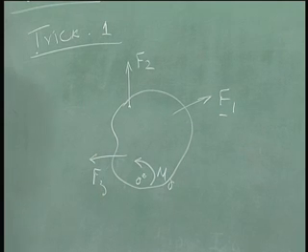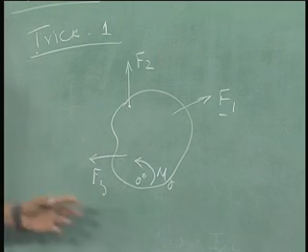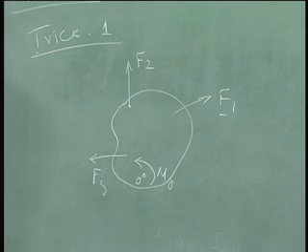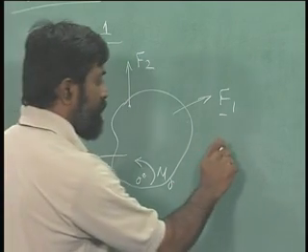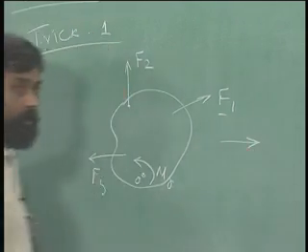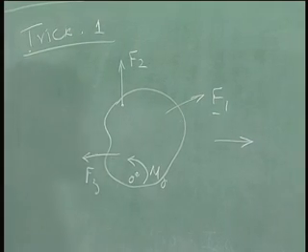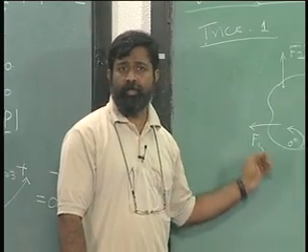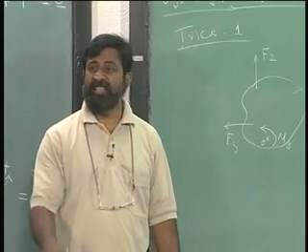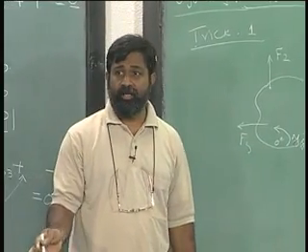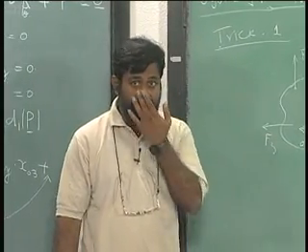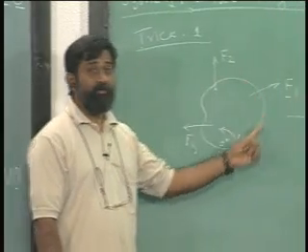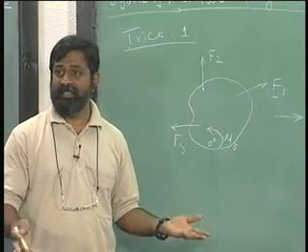I wish to find out the resultant force and moment. One of the important things to know is, one of the problems that we will face is which point should I take in order to find the resultant. The answer is any particular point you can take, there is no difference as such, because every point of this rigid body will be stationary.